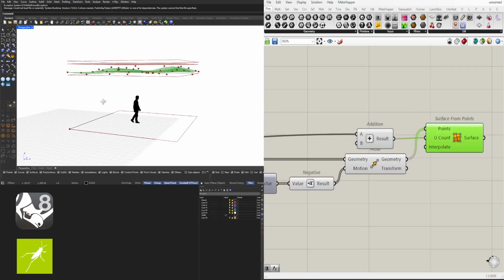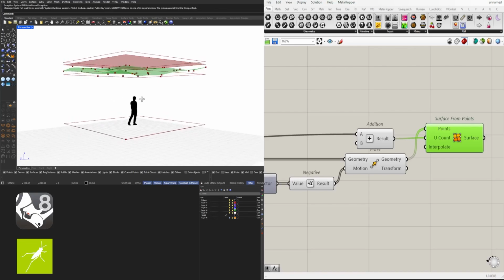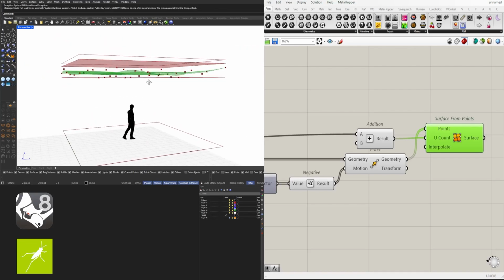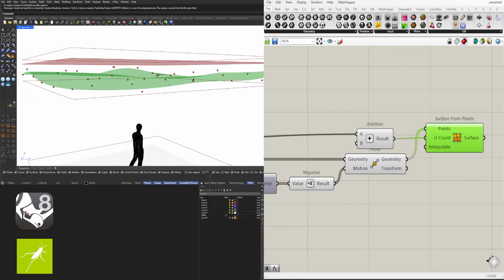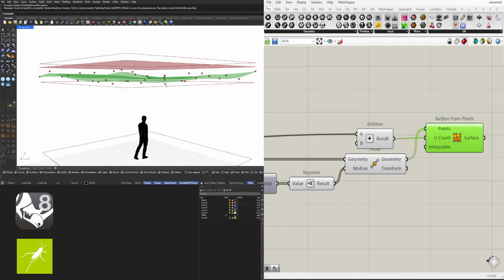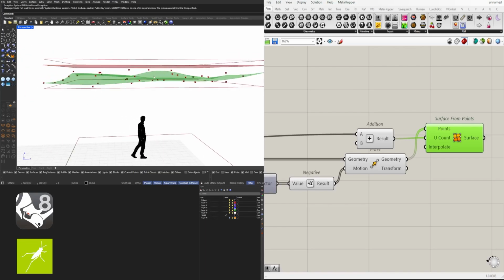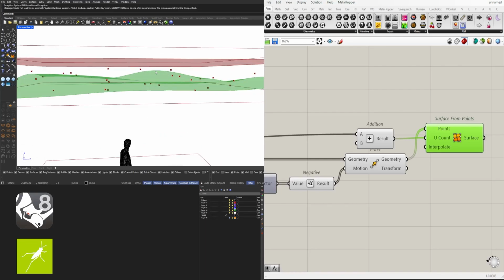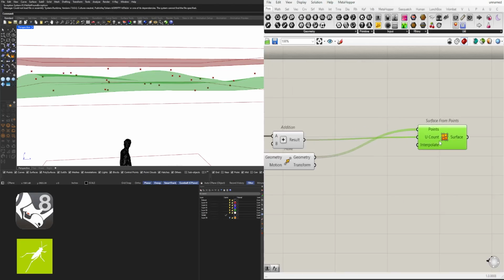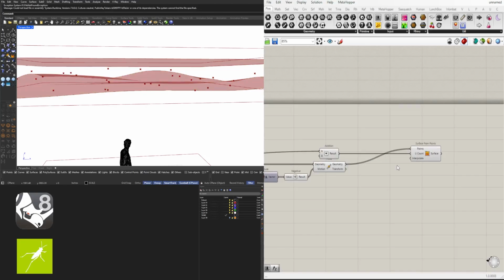And notice that now it creates that wave surface, although by default, it's not going to interpolate through the points, which means that it's not going to go through the exact points here by default. It says false. So you could have 2 different ways of doing this: interpolated and not interpolated. In the same way that you could have an interpolated curve or a NURBS curve.